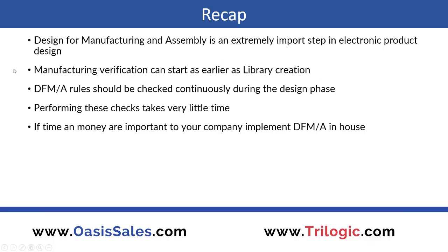Manufacturing verification can start early in the phase. A lot of people, even though they had Valor, would only use it at the end of the design process. You can actually start using this when you create your footprints at the very beginning. That just eliminates any future issues that you could run into or things you have to worry about later on when doing validation in the design. You can focus on more point things like component to component data and routing information. You don't have to worry about doing your footprint verification because your library has already been validated.